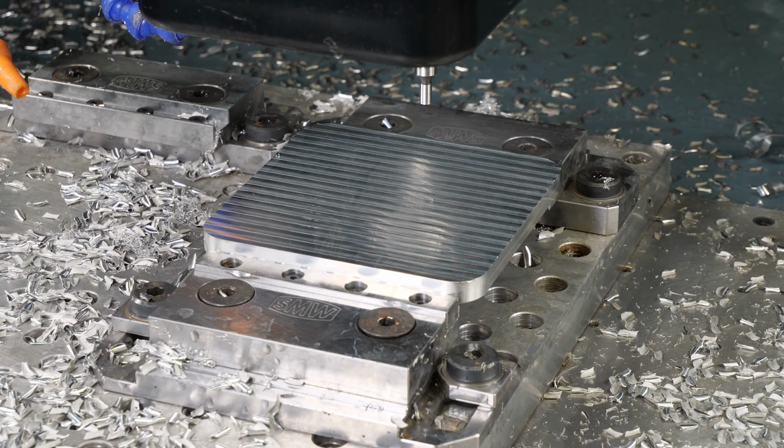And so edge finder is very useful if you don't have a probe, or if you feel like being old-fashioned. So now that we have our new X and Y, we're going to put our end mill back in. We're going to touch off our Z. And now, when we machine this side, it should be pretty darn close, pretty much near perfect to our other side of our part, and it's going to look real nice. So I'll catch up with you then.